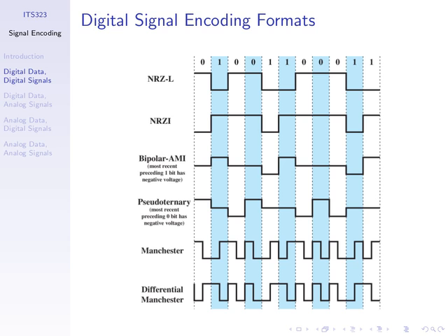What we do is we have 3 levels. 0 voltage, a positive and a negative. So we have 3 levels here. Bit 0, we have 0 voltage. And there's no line signal. So if we draw a line through here, this is the 0 voltage level. Whenever we have bit 0, 0 voltage.